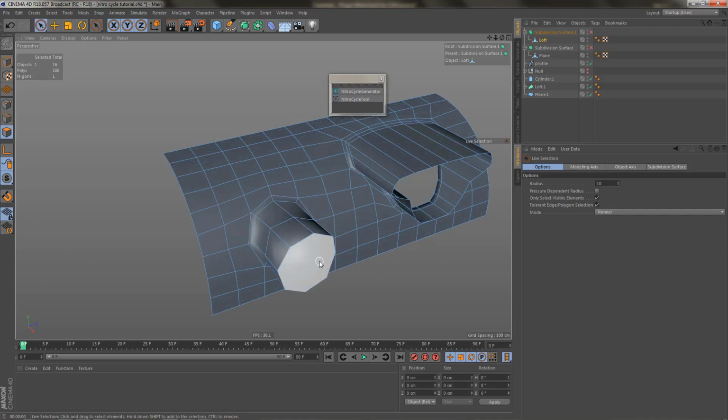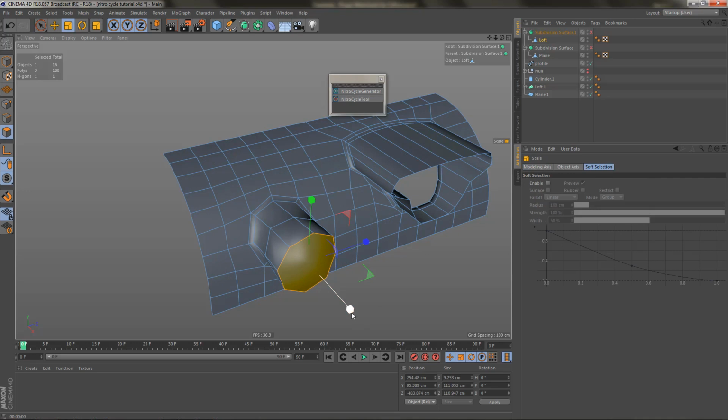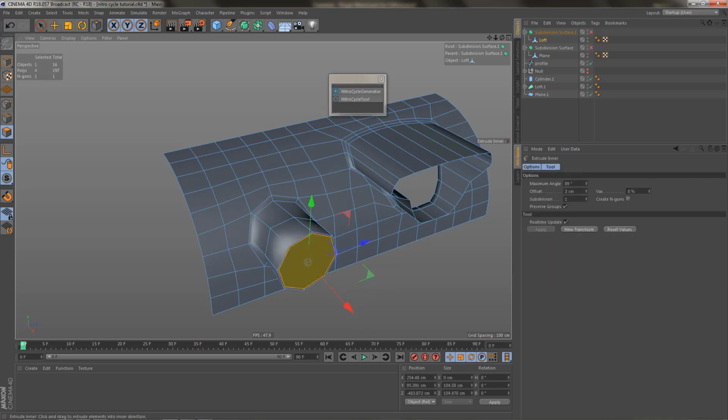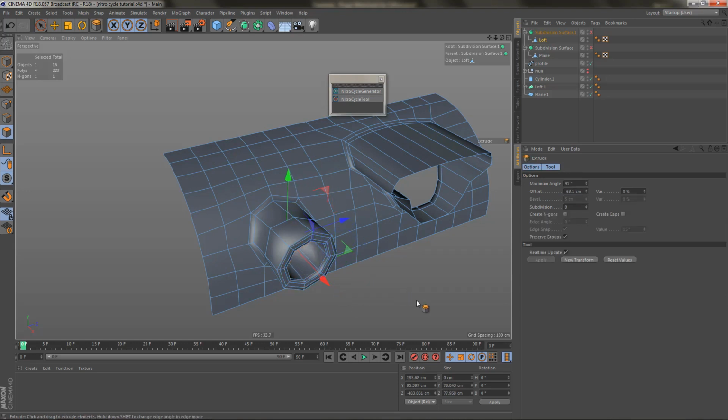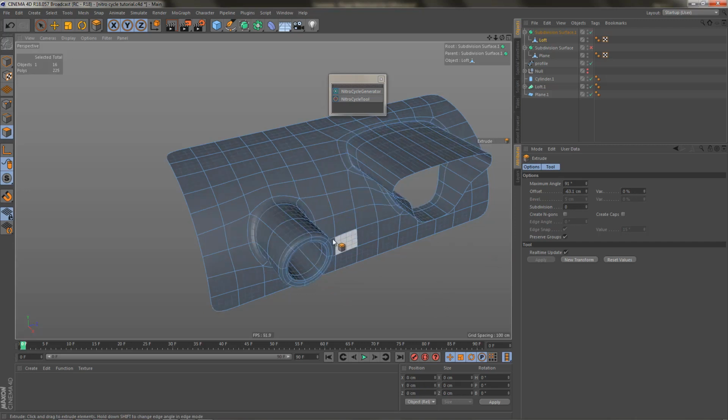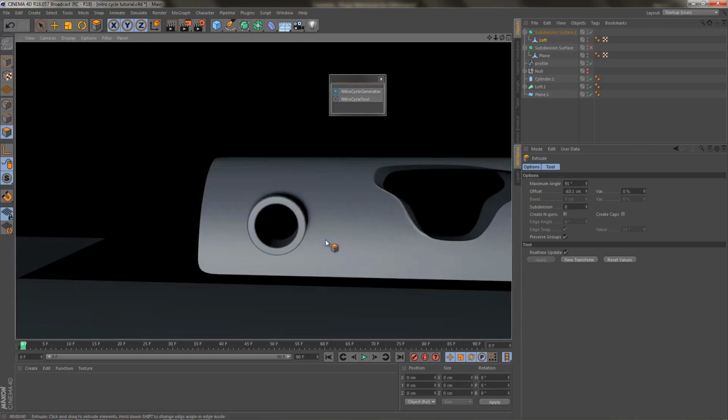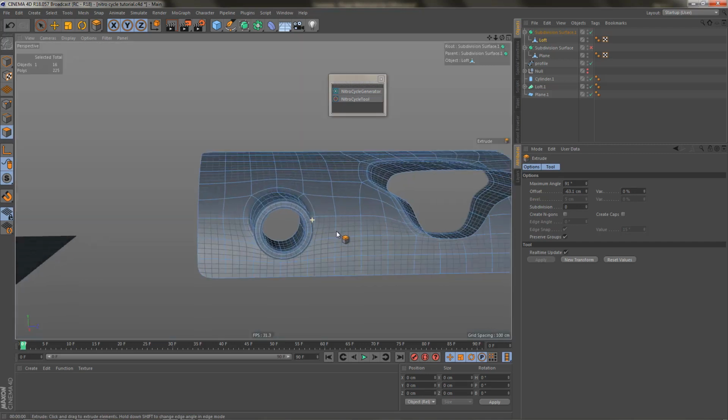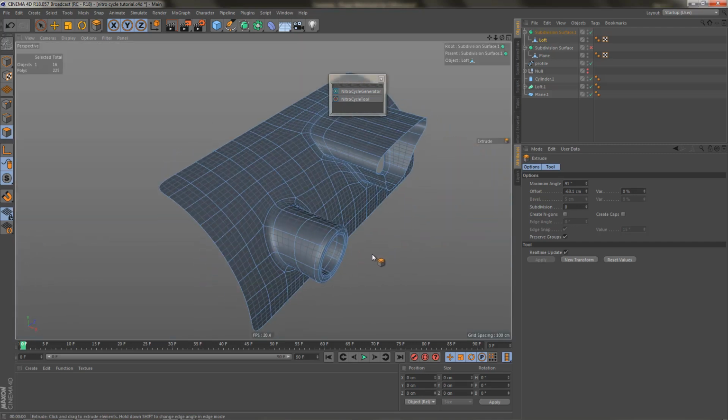and select these polygons, let's do, actually first of all I want to scale these down again. Let's use extrude inner, and I'll extrude this back a bit, subdivide this, and you can see now we have a perfectly circular shape, at least here at the front.